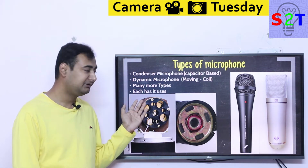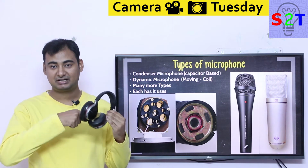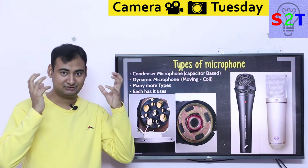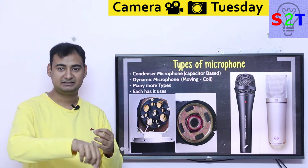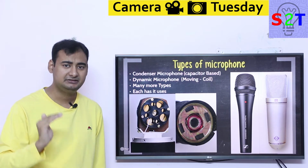Then we come to the dynamic microphone. Now what is a dynamic microphone? Basically take your speaker and invert it. Let's say you have a headphone like this. If you try to speak into this, especially the old one, don't try this with a wireless one. If you have a wired headphone, you can do this. Take the headphone out, speak into the earphone part, and change the cable there. It will work, but you will find the volume level is very, very low.